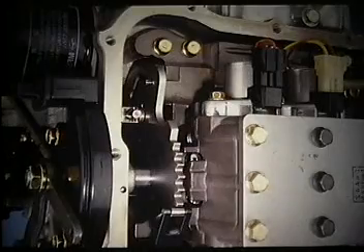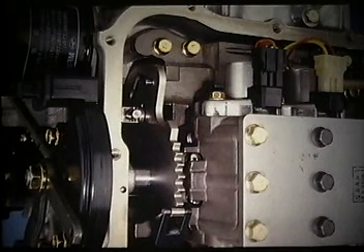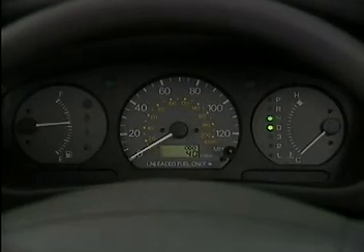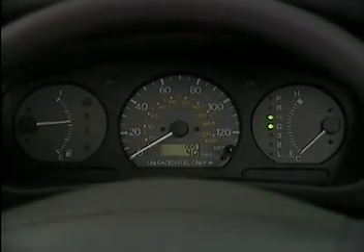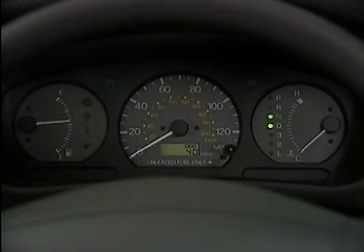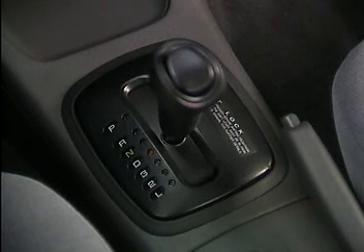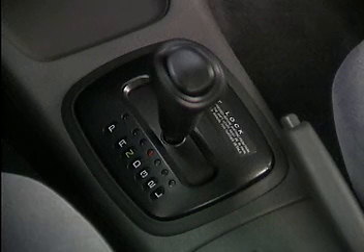A 3-position manual valve connected to the shift selector allows the driver to choose reverse, neutral, or third gear. If a malfunction causes the transaxle to go into fail-safe mode, the N-range light will flash slowly if the gear shift lever is in a drive gear. The service manual contains a list of conditions that will cause the light to flash.